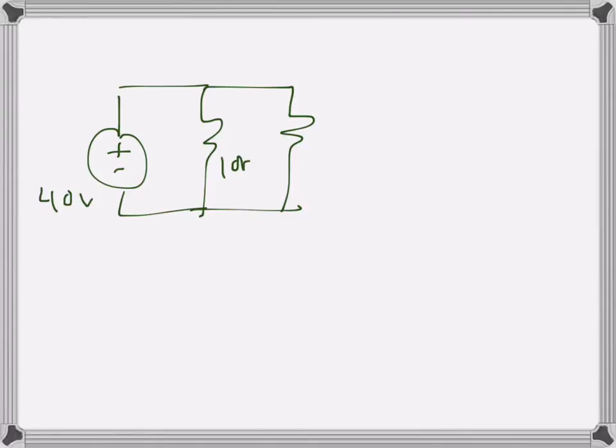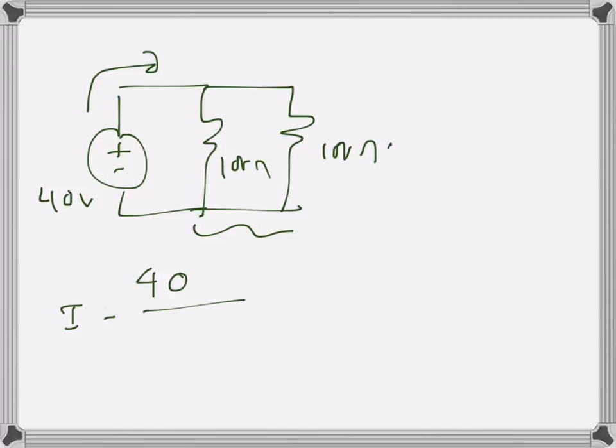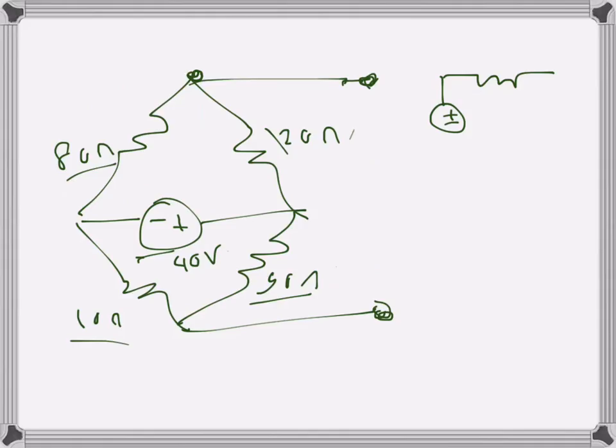So the total resistance is of course 50 ohms. So the total current that's coming out of it, the total resistance, that is 50, because the parallel of 100 and 100 is 50. So the current coming out from the supply, I, will be 40 divided by 50. So voltage divided by the total resistance. So that's 4 by 5 amps. So that is the current that is coming out of here. This one is 4 over 5 amps. Let's leave it like that.